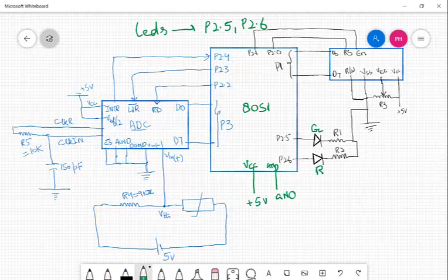We also have an LCD that we have connected, the data pins we have connected to port 1, and two control pins to P2.1, P2.0. What you are seeing here is the external circuit of LCD that actually powers the LCD and also controls its contrast. So that's okay. The outside is okay. At the input side, what actually we have?